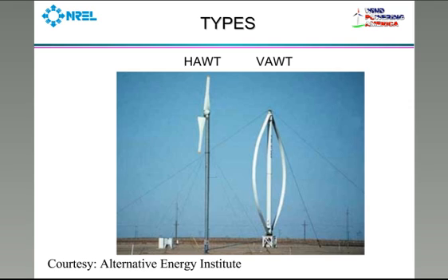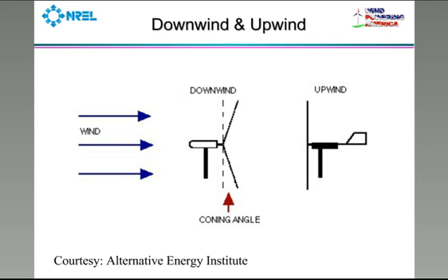for these large vertical axis wind turbines, they need to be guyed from the top, and so those guy wires go way out and they take up a lot of room. So this really prevents you from putting a big vertical axis machine on a tall tower, because then the guy wires would just become too unmanageable. So still a lot of interest. They technically work, but just the horizontal axis machines have gained more market acceptance at this point.